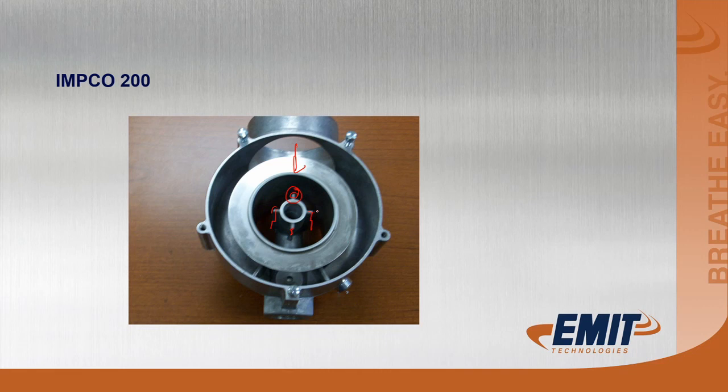If there is, throw the carburetor away. There's no repairing for that. And too many guys will fight them. They get hard starting. They have troubles meeting emissions because the emissions are erratic as it jumps over the shoulder that's worn in there. The wear spot is normally right where the engine's carrying the load most of the time, and any deviation from that makes it challenging to meet emissions.